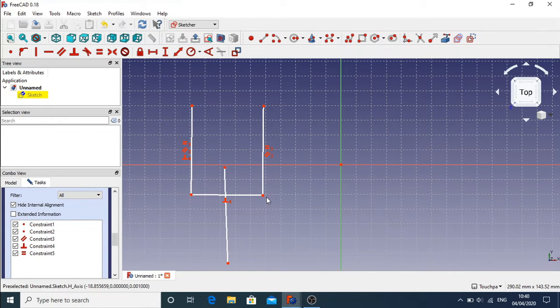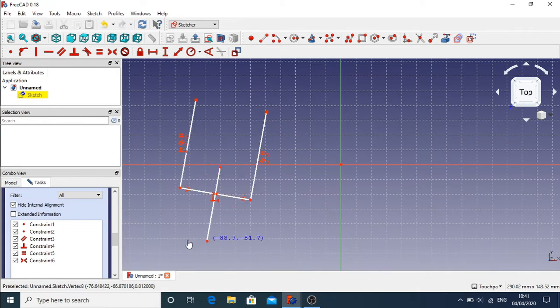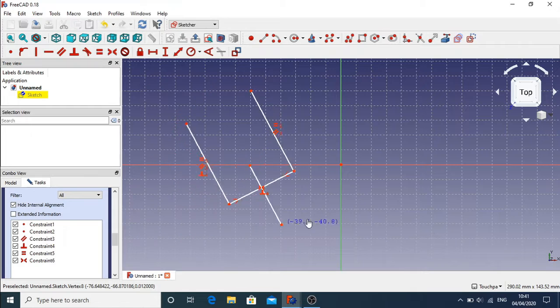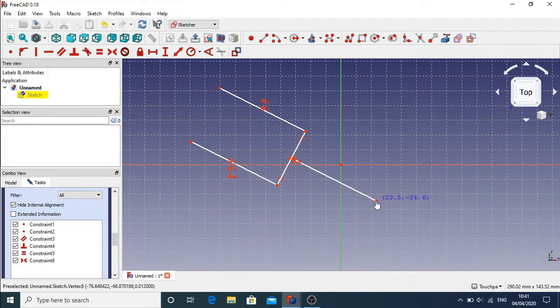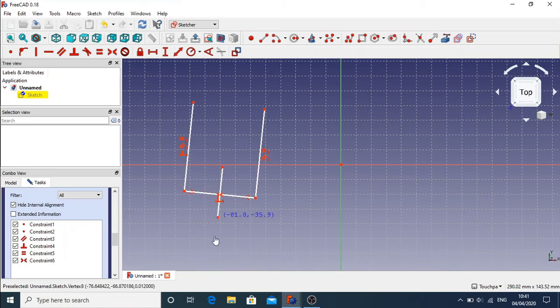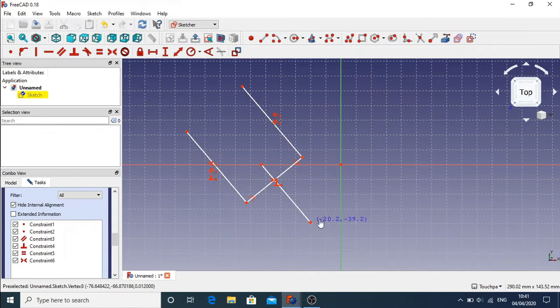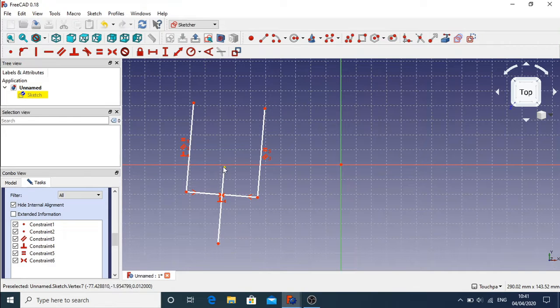Let's get rid of that. So click this point, and this line, and hit the symmetry, and that will be slap bang in the center between these two points here. So I can move this now, and you'll see that that will actually move and be symmetrical. Now my line moves up and down as I'm moving this, so I can actually attach this point to this line here by clicking on the point and the line and using the fix a point onto an object.